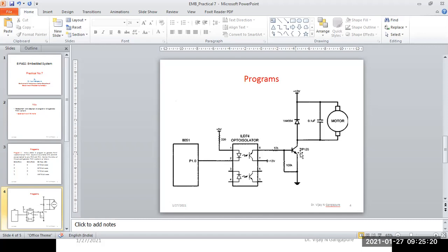So the PWM generated on this pin will supply power to this motor only for 25% of the duration out of 100%. Due to that, this motor will rotate with 25% speed. If the switch positions are 0 1, then we are generating 50% duty cycle PWM, due to which 50% power will be delivered to this motor, and motor will rotate with 50% speed.